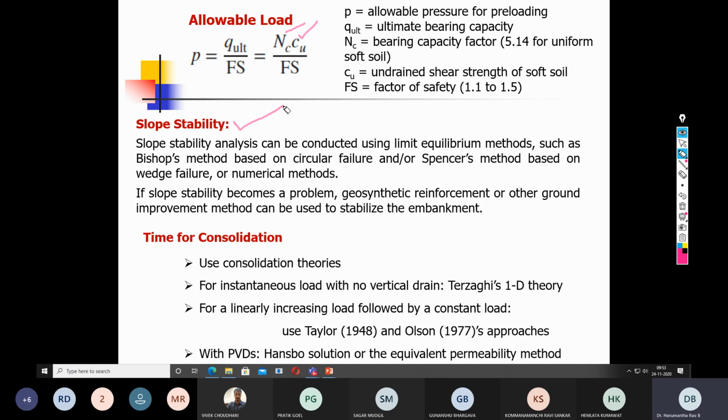This is one of the most important factors when you deal with sand drain technology in a soft soil. If you do not understand the minimum bearing capacity, then most of the time you may end up with slope stability failure. This slope stability failure occurs like a base failure, because you have a soft soil in the natural condition, and on top you construct an embankment, which is compacted, but the bottom soil is under undrained condition without any compaction.